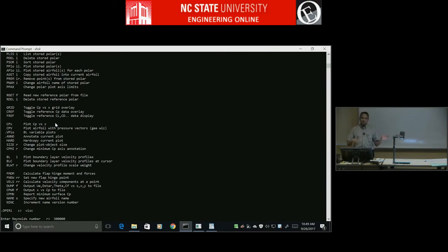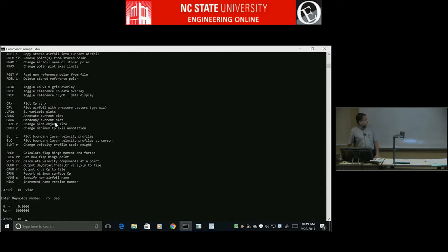I'm telling you these things because over time I've made mistakes and then realized, that was a silly mistake. But these are human factors things, right? You won't notice it. So you can do 3E6, and this is a better, more foolproof way to enter the Reynolds numbers. This way you're very clear that what you think you're putting is what you're actually putting. So now it tells you, okay, Mach number 0, Reynolds number is 3 million. That's what it's going to run the airfoil at.